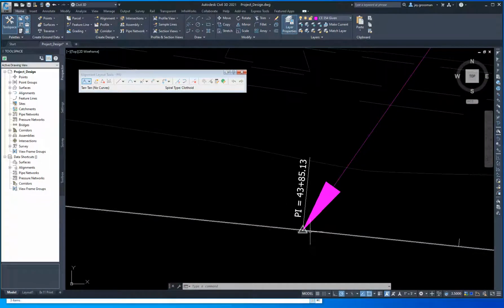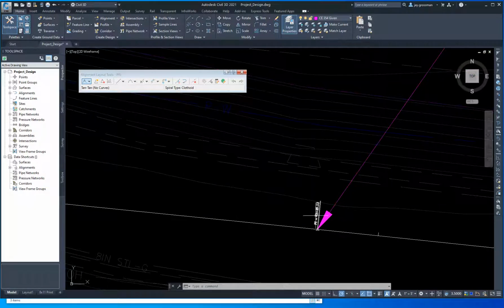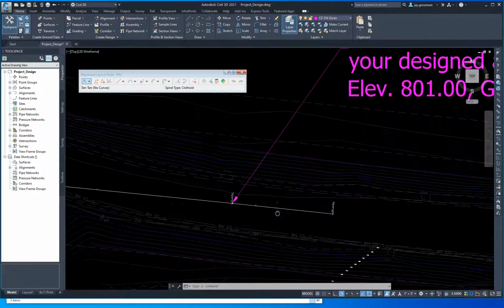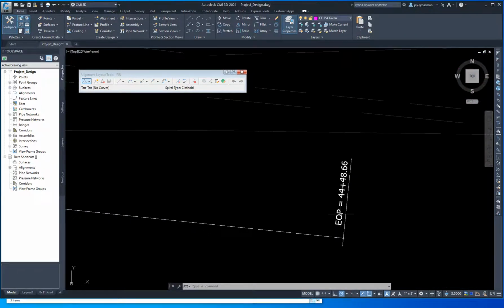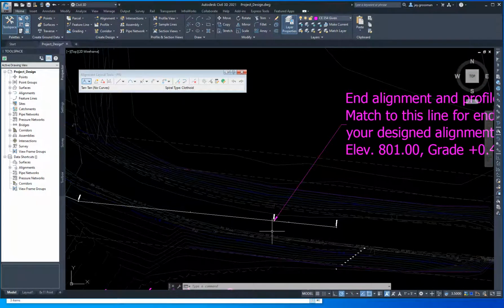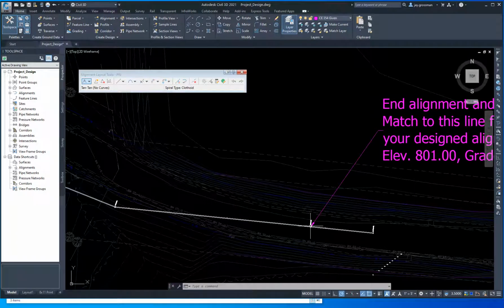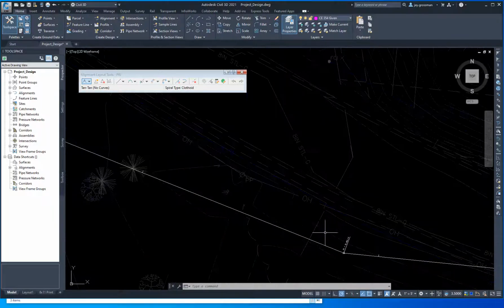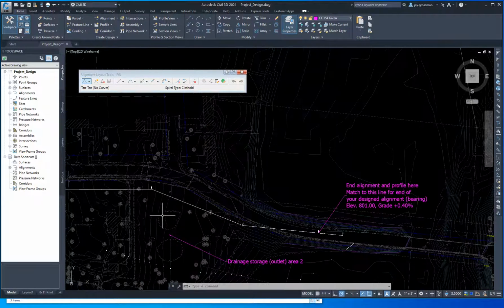If you zoom in now, look, I have set PIs. I have set points of intersection, and it gives me the station number. Right? We are now 3,300 feet past where we started. Right? This is over half a mile. And here's this one. My end project is down there. And so I technically need to end here, but I added this extra piece in just to make sure I get this thing straight and correctly lined up for that. Here's my other PIs, right, for that.